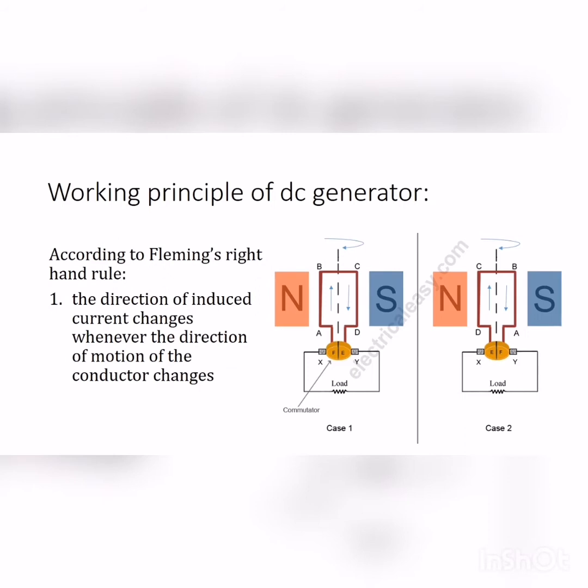If you look at the above figure, you will see how the direction of induced current is alternating in an armature conductor. But with a split ring commutator, the connections of armature conductors also get reversed when the current reversal occurs, and therefore we get a unidirectional current at the terminals.